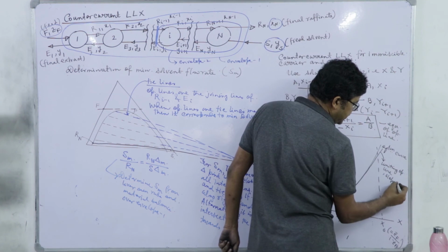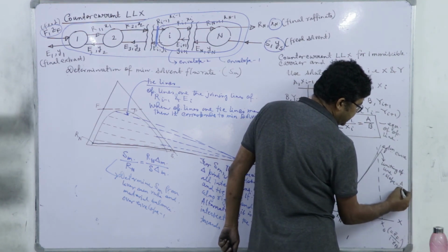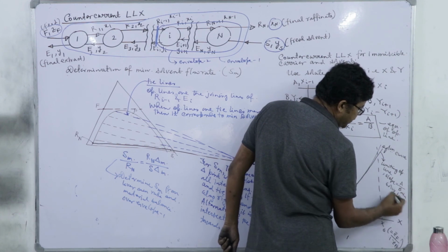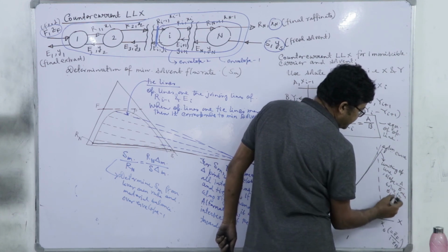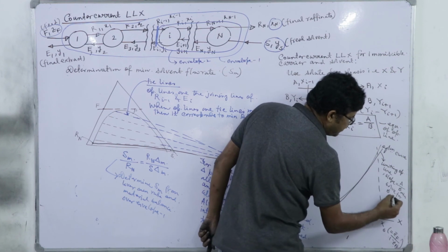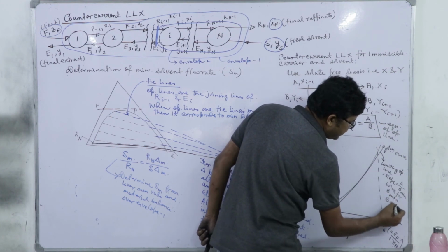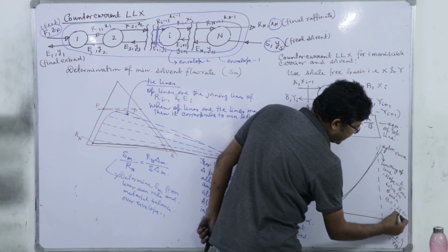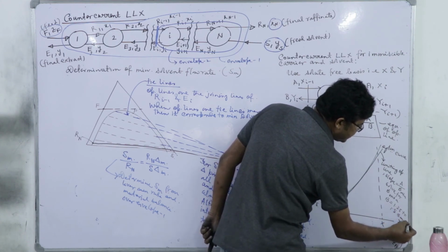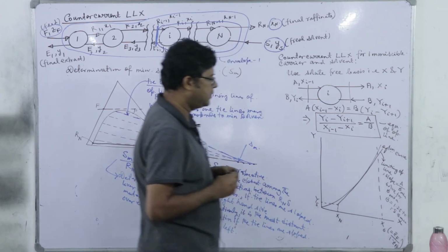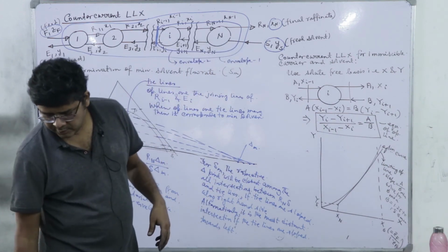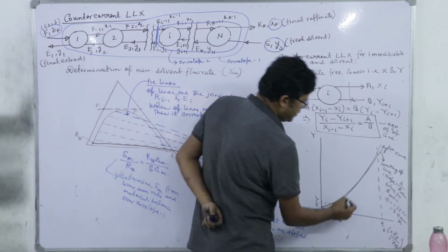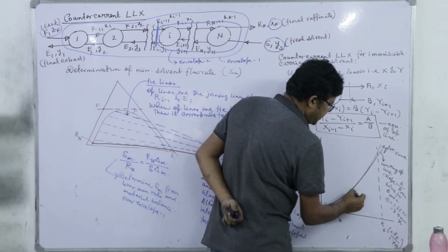So, this is just like the previous cross current extraction, that is the limiting operating line. Slope is A by B minimum, solve for B minimum, and B will be 1.25 to 1.5 times of B minimum. Right. So, you have determined the minimum solvent flow rate and therefrom the operating solvent flow rate.